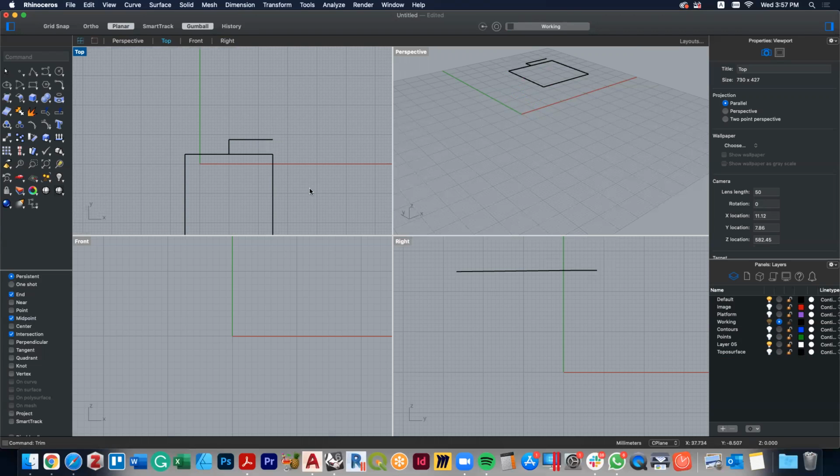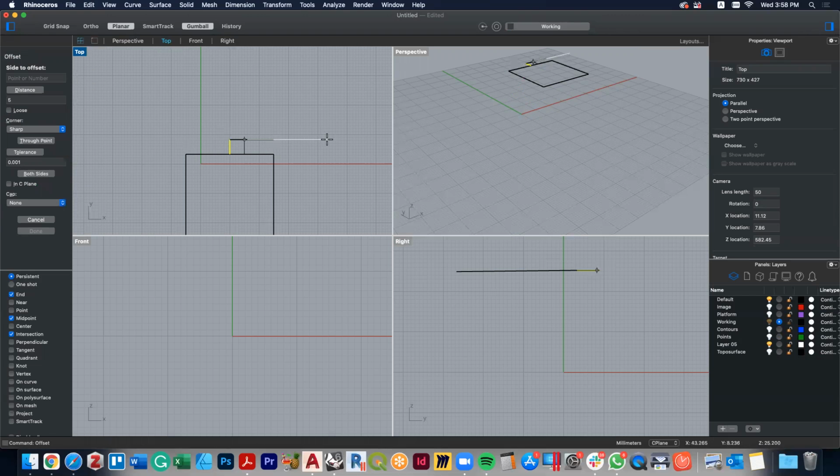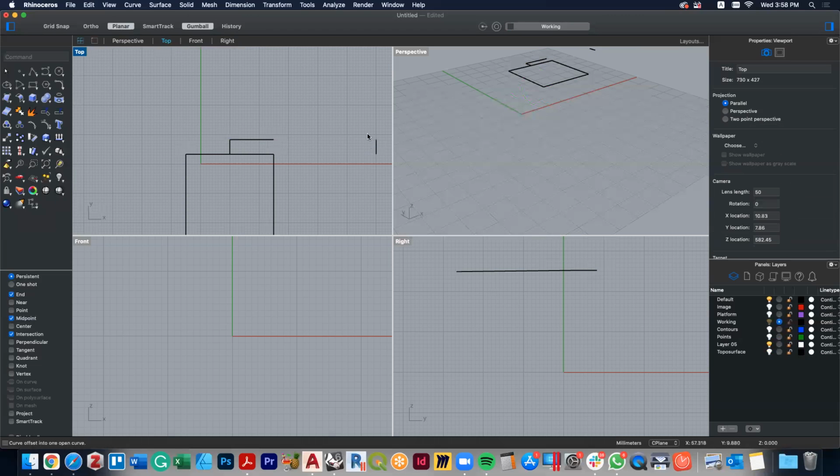One of the things I've learned through doing this assignment is we need to have quite a bit of space to work with. So I'm going to create quite a large cutting plane. This is a plane which is really setting up the angle of where the swale base is going to be. So if I offset this, and I type in 50, because it's actually going to be a 1 in 50 slope, which is what he specifies, then I offset it there.